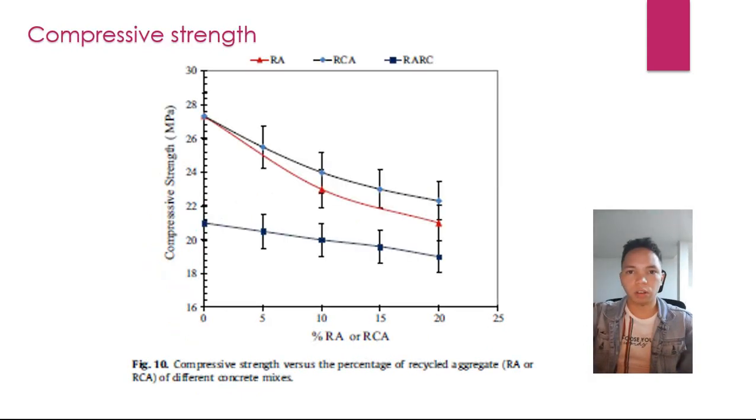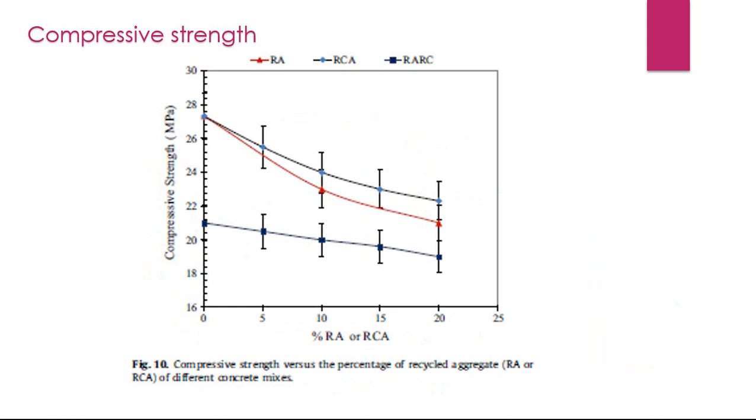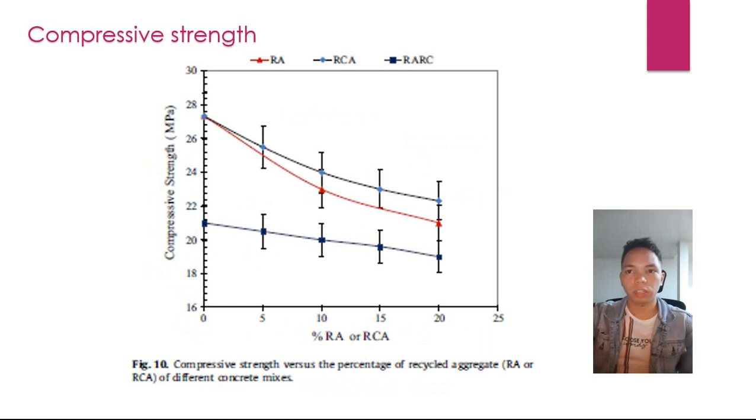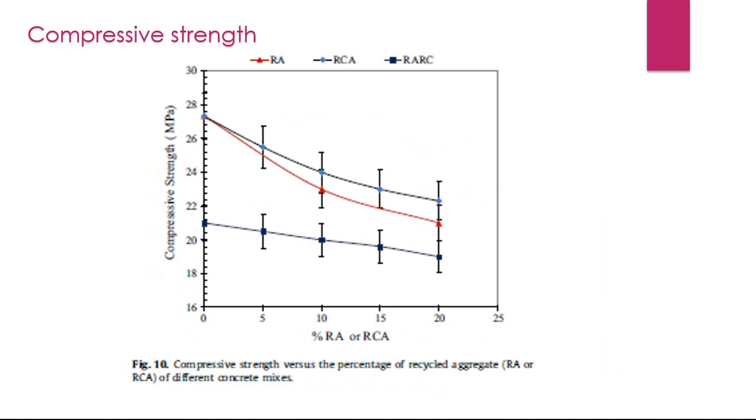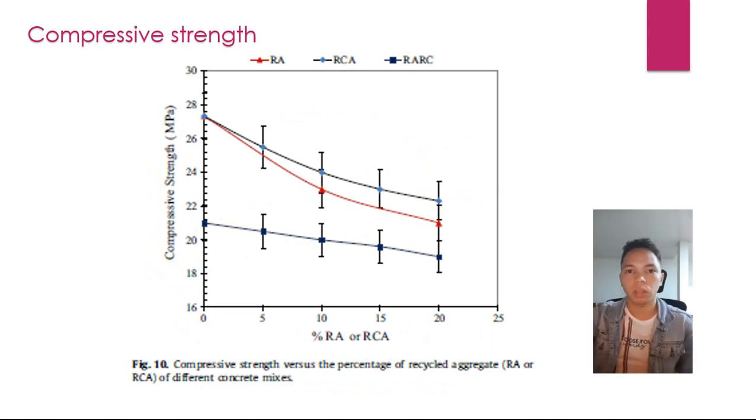The average of 3 compression resistance cubes for each mixture is shown in Table 3. The percent reduction in the compression resistance of concrete incorporating 20% RCA was 18% over the reference mixture. The percent reduction in the compression resistance of rubber concrete compared to conventional concrete was found to be 19.5% for the replacement of 10% of rubber.